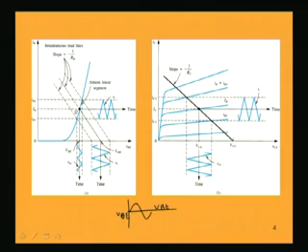Now, the corresponding plot in the output: if we look into the output characteristics, the output characteristic is nothing but a plot between IC and VCE, and here it is instantaneous current and instantaneous voltage, a combination of both DC and AC. So, corresponding to a particular IB, we have that particular value of IC.